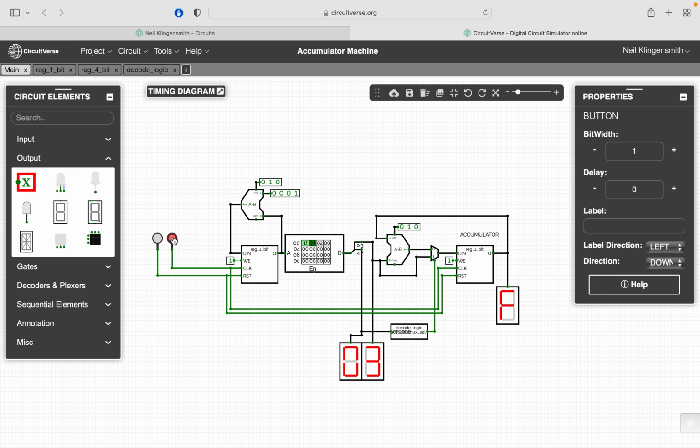All right, and then if I hit this clock button, you can see that we have inserted the number F into this accumulator value, right? And the next instruction is going to add 3 to that, so F plus 3 is F, 0, 1, 2, so the output here should be 2 on the next clock. Let's do that. There's the 2, then we add 2 to that, that's going to be 4, and so on. Then the rest of the instructions are all zeros. They're not going to do anything.